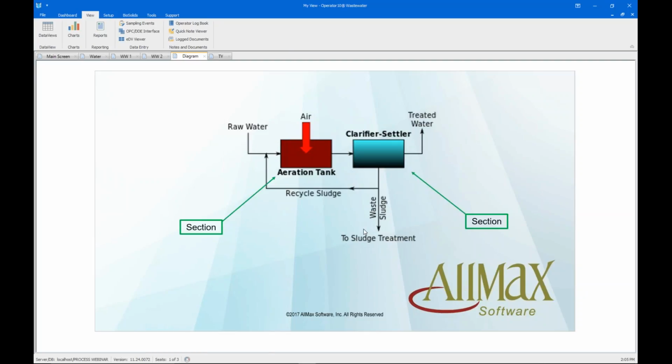We're going to be dealing with a wastewater treatment plant today. Process-wise, you may have several different types of processes in it. You may have a primary process for your primary tanks, where you want to see removals and efficiencies during that section of your plant. You may also have your secondaries, which could be aeration basins, trickling filters, or clarifiers. Again, that information is going to be there, and you're going to want removals based on that type of process.